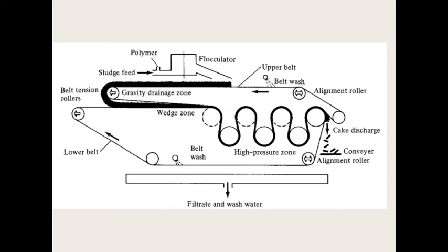Then purification and compression of the biogas, methane, which is converted into natural gas and used for power generation, and that power we can use on site. The remaining sludge we can further separate and digest and use as a soil enhancement, or as soil conditioner. In this way we can produce energy from sludge, the sludge to energy system.